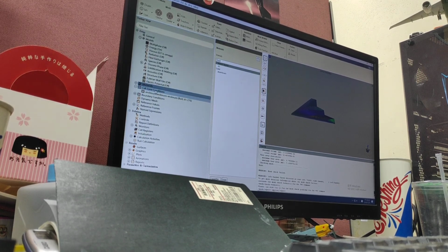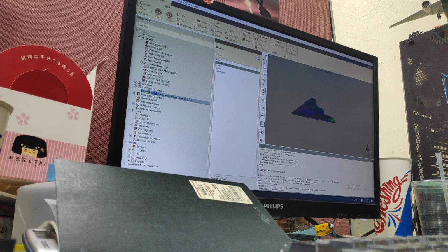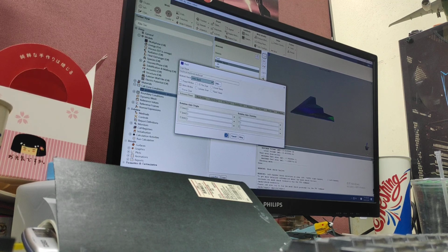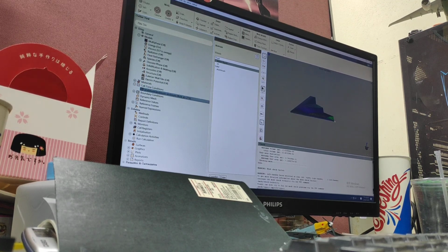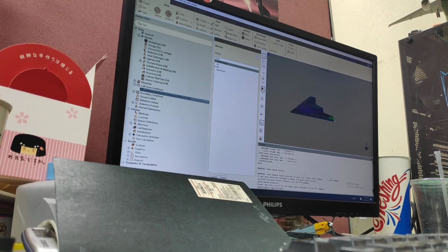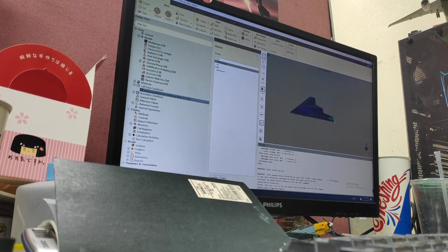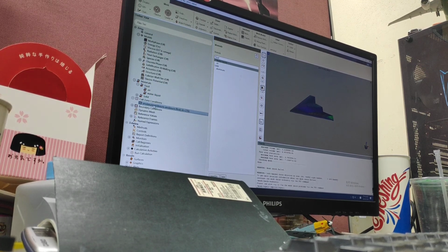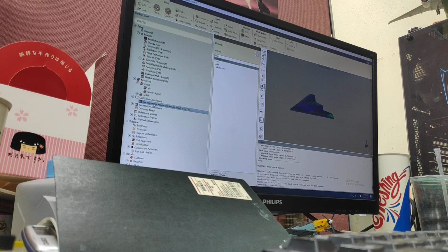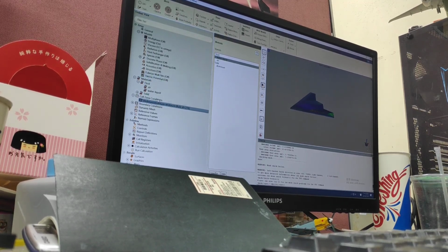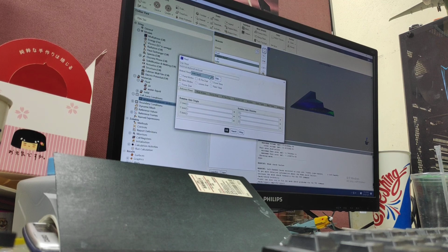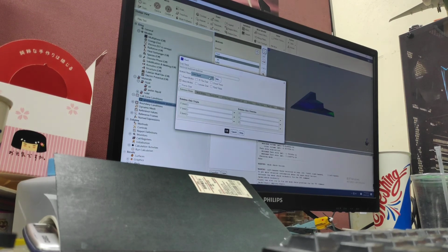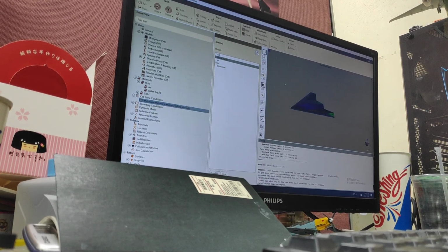So here is your cell zone. Click here, and then you can change your material to water. Okay, so now you're using water. So you have to change it in two places: both materials and cell zone. So we choose the water for our calculation in the whole domain. Okay, so it's up to you.